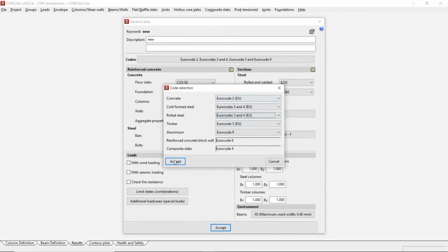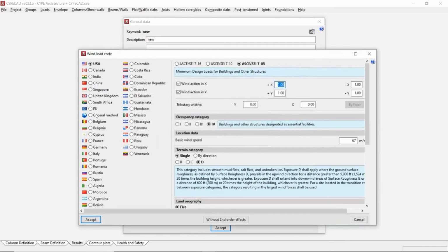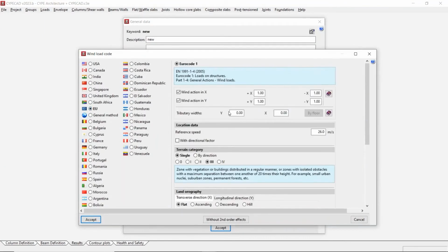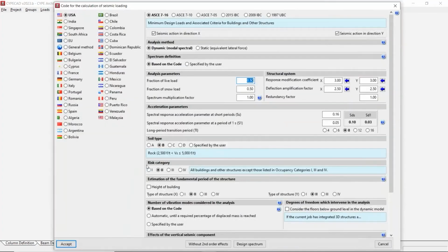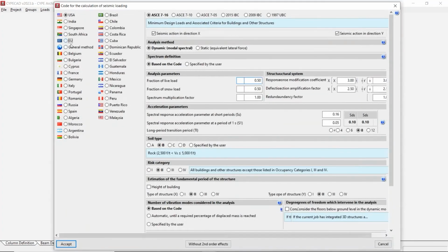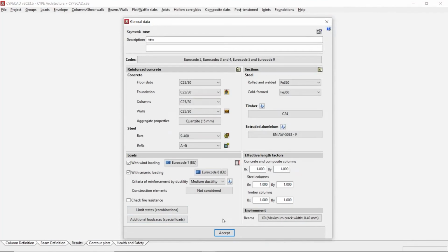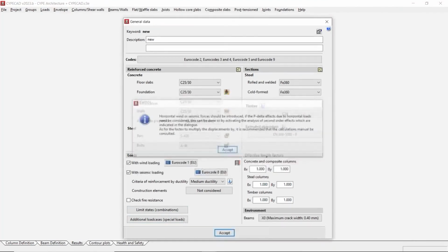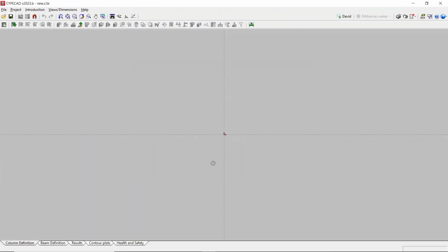The setting up process is the same. We're using the same panel we were using before, just instead of using a 3D model, now we're using a 2D CAD file. So from there, we'll just get in and start working. There are a couple of things I wanted to mention in that regard. I'll wait for David to get there, but AutoCAD is really finicky with scales.